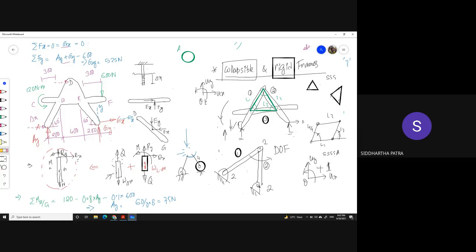If two rigid bodies were not connected, each of them had 3 degrees of freedom, a total of 6 on a plane. But connecting them with a pin joint takes away 2 degrees of freedom, so now you are dealing with 4 degrees of freedom of the structure, if not constrained by the ground. To have a structure in equilibrium, the ground also must provide the remaining number of constraints, which is 4.